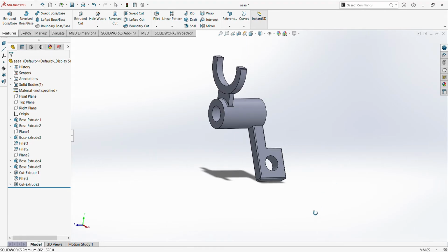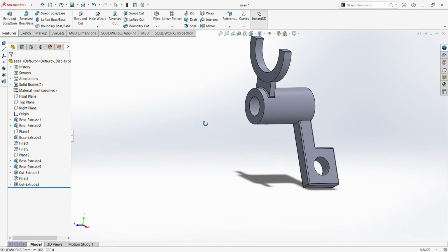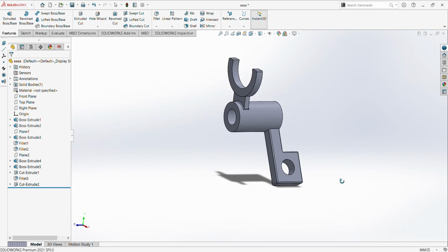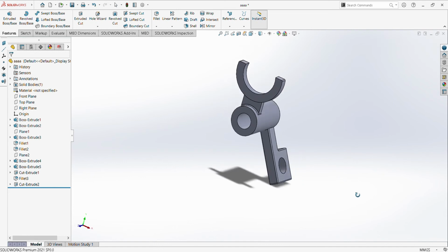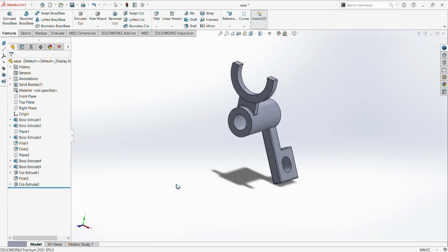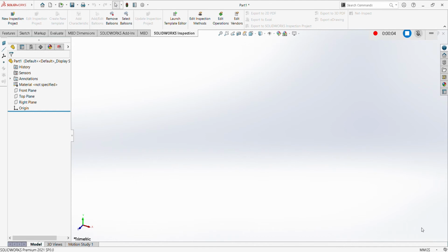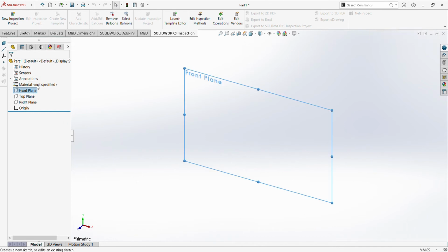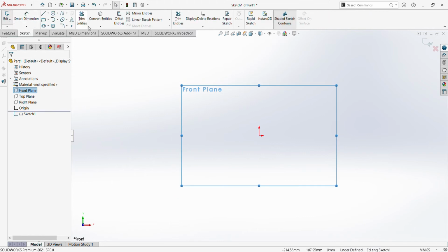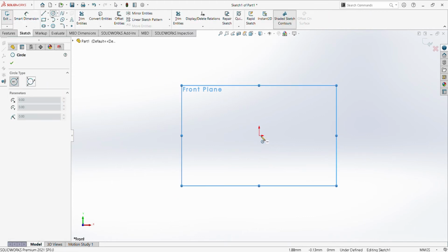So first, we will be doing an activity based on this 3D model through the use of the SolidWorks app. To start, the units to be used is in mm, and we will change it here. Then we will proceed on the front plane, click Sketch. Next is to draw a circle, and then using Smart Dimension, type 28.